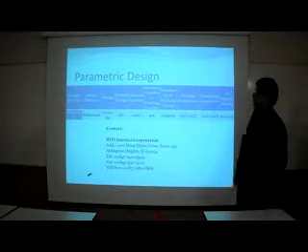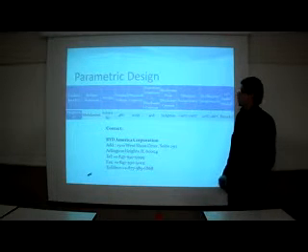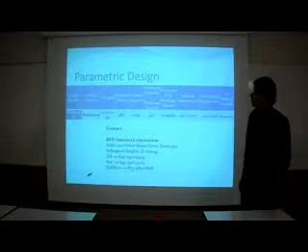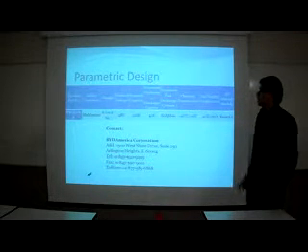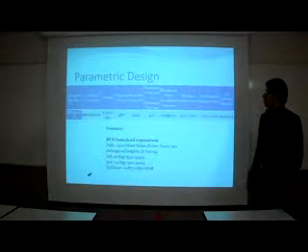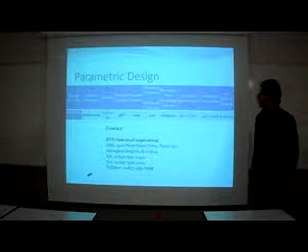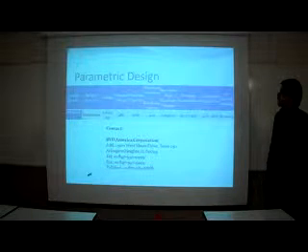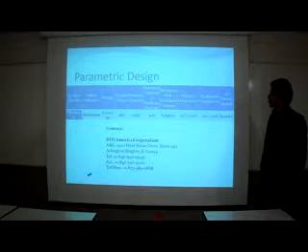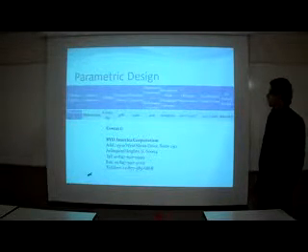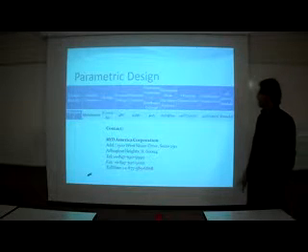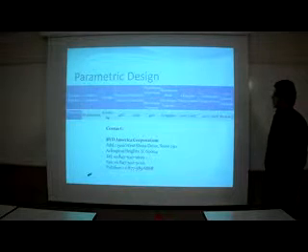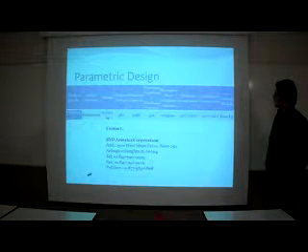Now talking about design, our battery structure must be modularized. The weight will be 11.2 kilos. Nominal voltage about 48 volts. Nominal capacity 20 amperes. The maximum continuous discharge current will be 40 amperes. Maximum peak discharge current will be 60 amperes. Charging temperature will be plus 10 degrees to plus 50 degrees.